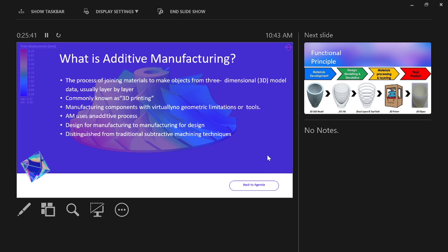So it is made by another method, that is polyjet technology. Polyjet technology, in which multiple jets are there and the material is in the form of liquid. Okay, and droplet by droplet this material is deposited and through UV light it is cured. Okay, solidification happens with the UV light.